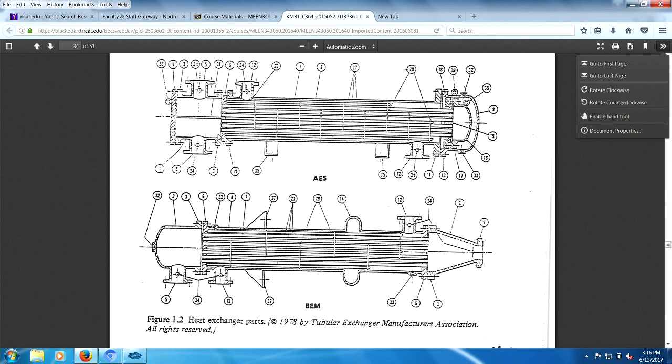Straight insertion. No damages, no forced tube sheets. Well, you got to force it somewhat. And then you probably want to watch how they weld. There's a little weld that could be around that tube sheet as well. Anyway, that's the second hold point.